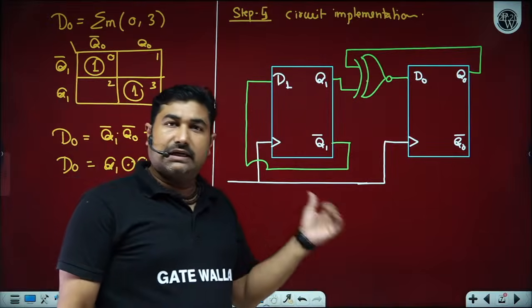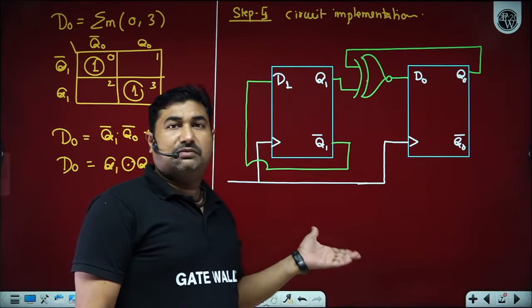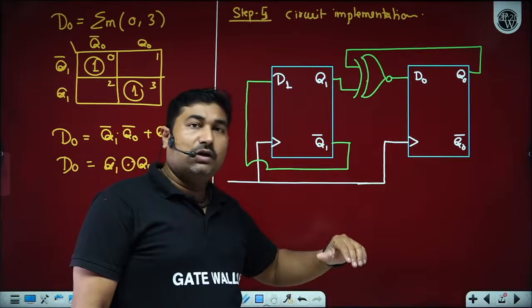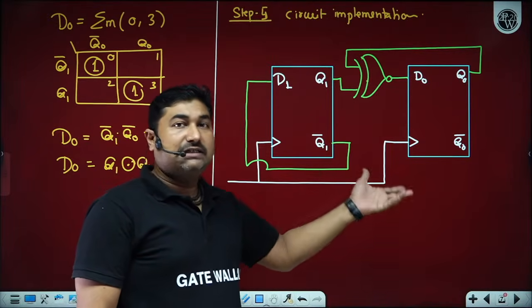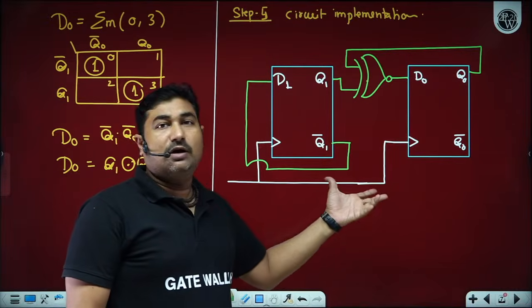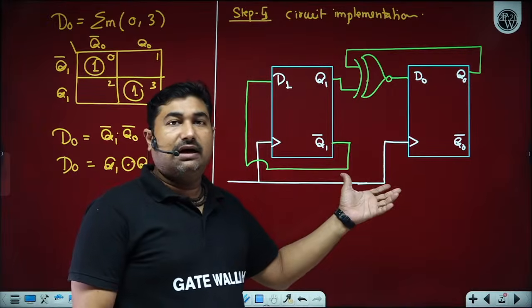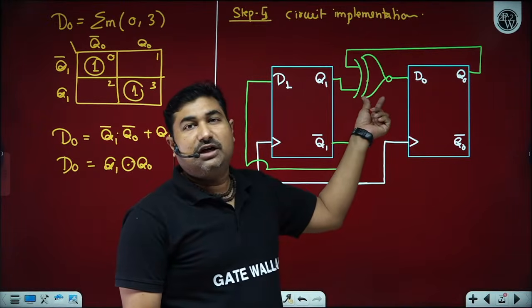In order for the circuit to operate satisfactorily, we must keep the time period of the clock such that all the logic gates will operate before the next clock comes, as well as the flip-flop will operate. Since both the flip-flops are connected to the same clock, only one TPDFF, propagation delay of the flip-flop, and one propagation delay of the XOR gate.